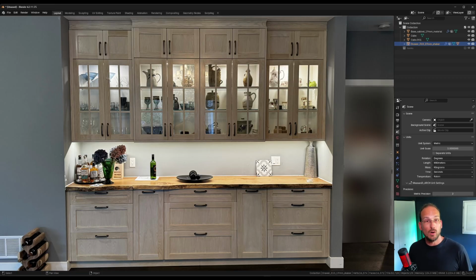Now, of course, if we go away from the wall with a cabinet, that leaves a gap, and those we fill with trim pieces. And if we have visible cabinet body sides, then we use a panel, and those should all be made ideally from the same material as the front. That way you have continuous material in all the visible areas. Now, depending on the situation, there are, of course, more things that we need to consider, but that depends on the situation, and there's just too many things to list them all.